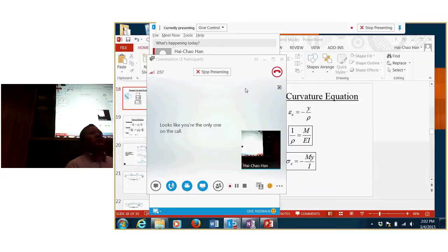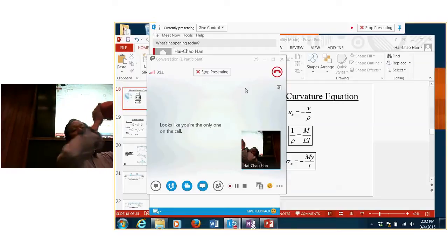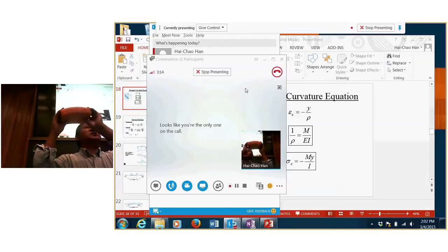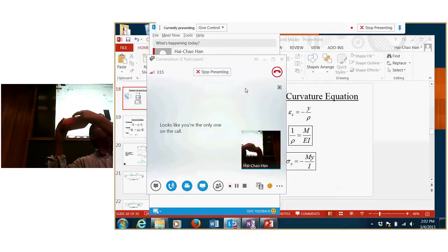All right. So last time we talked about stress in a beam. When you have a beam that undergoes bending, there's going to be normal stress, right? Remember we used this form to demonstrate. When you bend the beam, you're going to see that one side is stretched, the other side gets compressed. And the lines, if you see the cross sections, remain as straight lines. So the plane remains a plane. So we have the plane assumption, right?